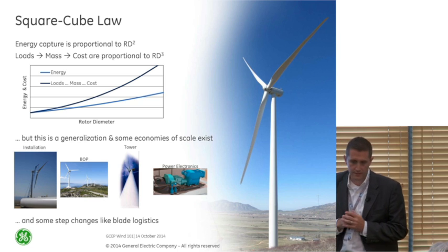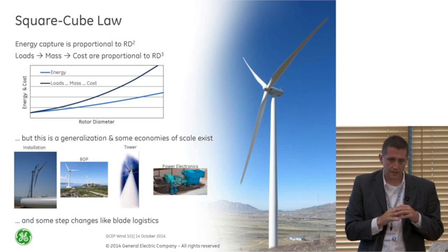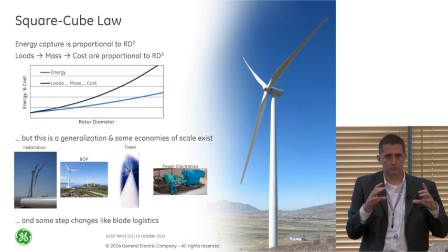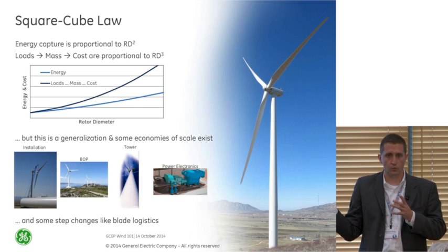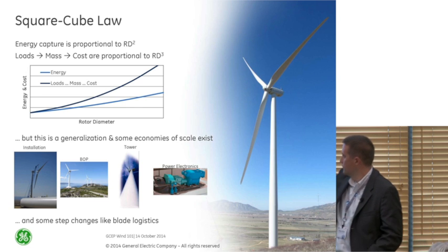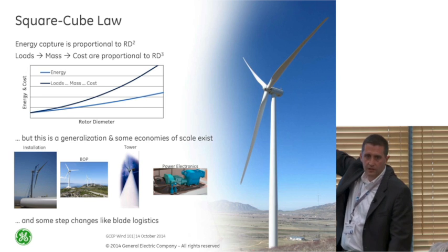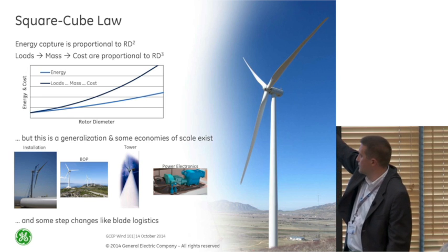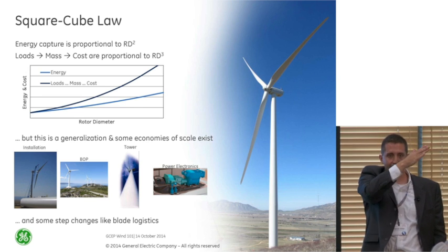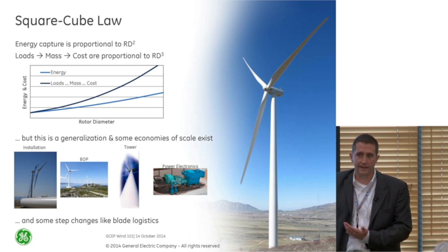And there are some economies of scale in the power electronics. Based on all of these economies of scale, you have really seen where the thing lands. You have this decreasing cost from all these things, and you have this increasing cost based on rotor diameter. You'd think it's going to settle out to some sort of optimum, and that's sort of what it does.